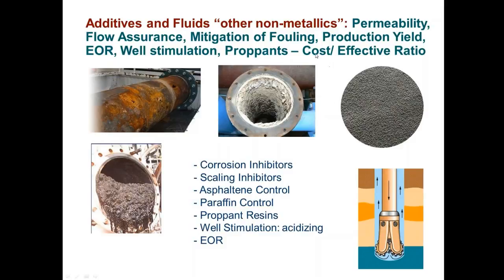casings or the drilled field. Over time, scaling can occur, which comes from sulfates, magnesium, calcium, different types of phosphonates. Paraffin can be in the form, of course, of deposition of waxes or asphaltene, which are some of the natural surfactants present in oil. Both paraffin and asphaltene are a huge problem, which can result from low pressures, low temperature, flow conditions.